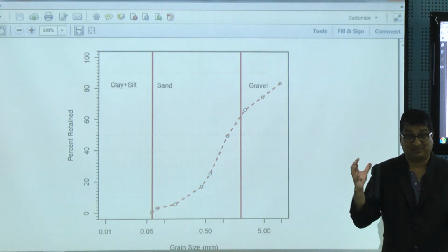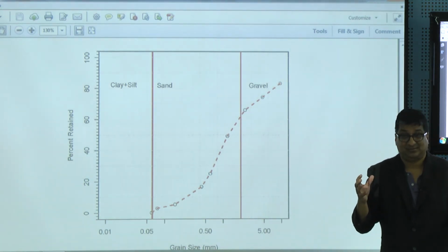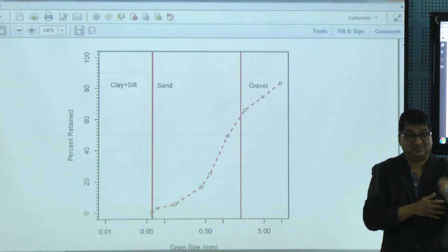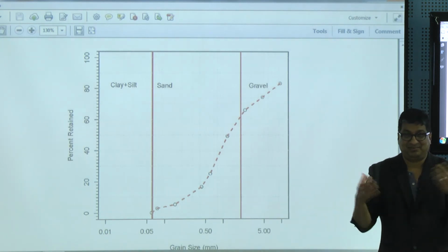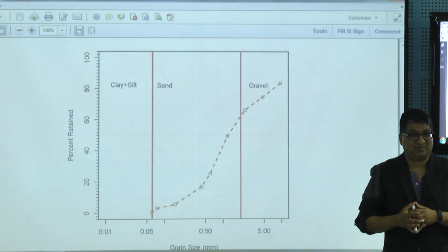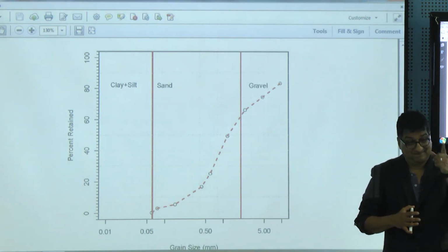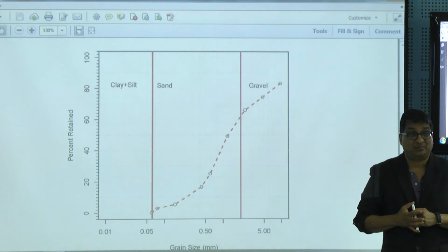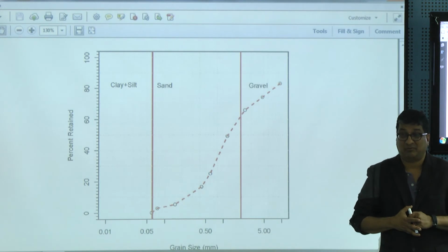Gravel has a lot of big pores, right? So there'll be a lot of water. So why not put it in gravel? Connectivity is beautiful. It's got nice big pores. One pore connected to another pore. So it's very easy to pull water out of a gravel because the pores are very big. Which means your aquifer will get drained very quickly.